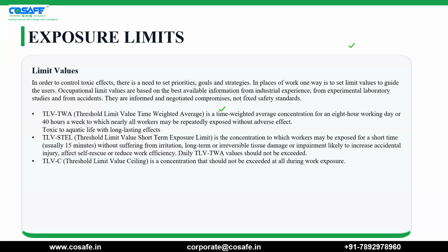So TWA is an average time in an 8-hour working time. If a person is working in an 8-hour shift, there is an average time that a person can be exposed to a certain kind of hazard so that they should not be affected by the hazard and they can do the work safely. That time is known as time weighted average, the average time a person can be exposed to a hazard in an 8-hour working shift.